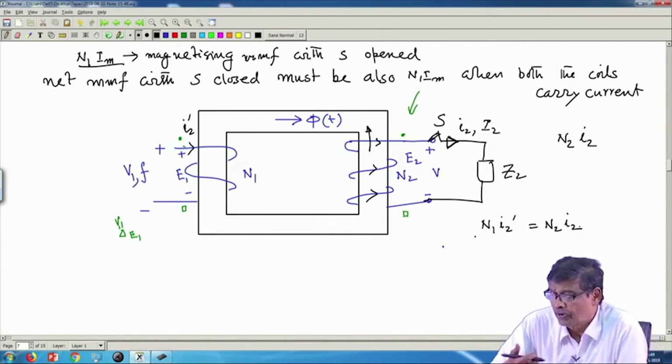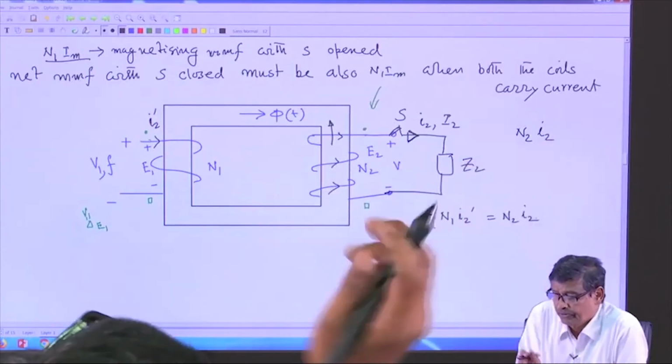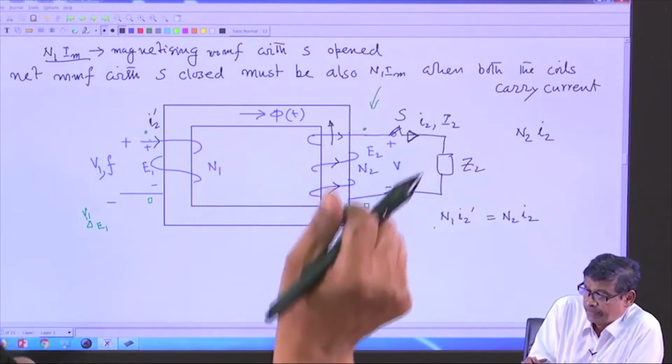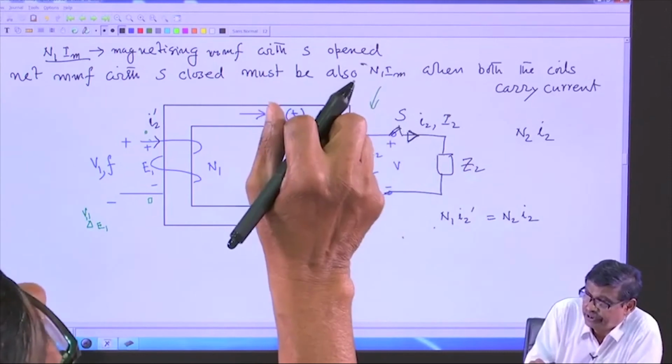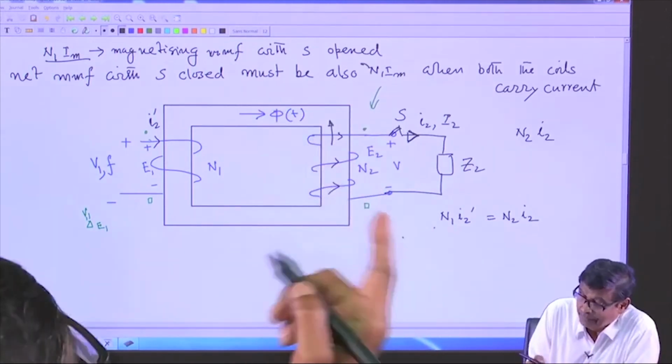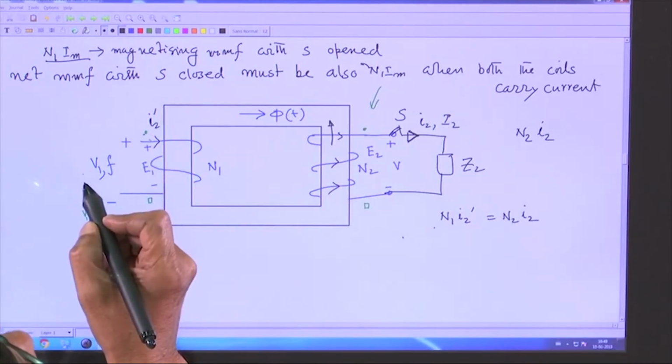Therefore, I want to draw current from the secondary of the transformer. I know then it has produced an MMF N2 I2, which is acting in the anticlockwise direction, it tries to create flux. But I am telling the moment you do that, primary draws extra current.